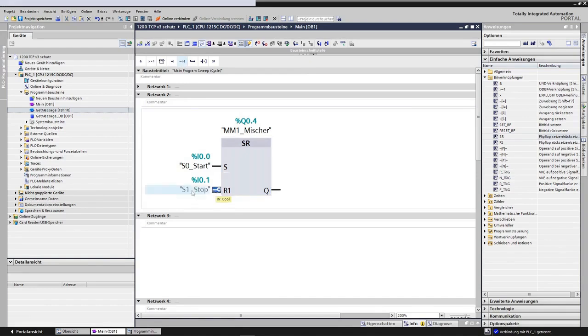That is indeed a very good input, certainly. If you want to remove the inverter, please do not try to delete it using the delete key or backspace. But you just need to click here once and then click the same component in the shortcut bar again, and then it will be gone.